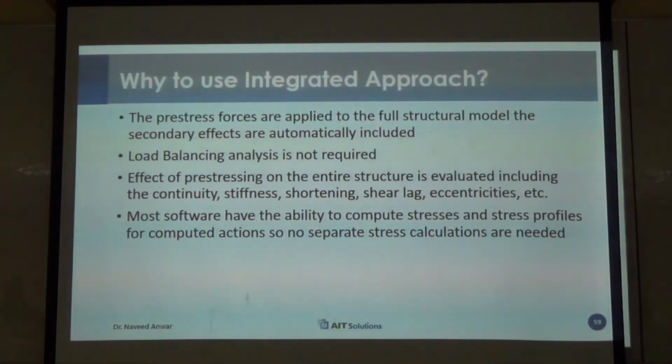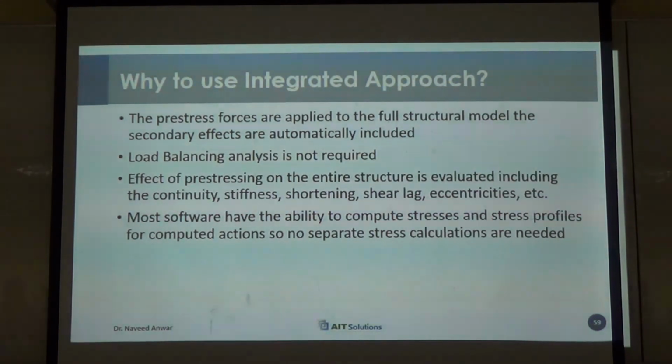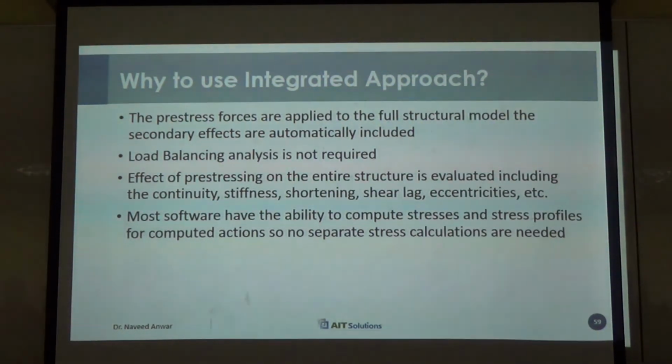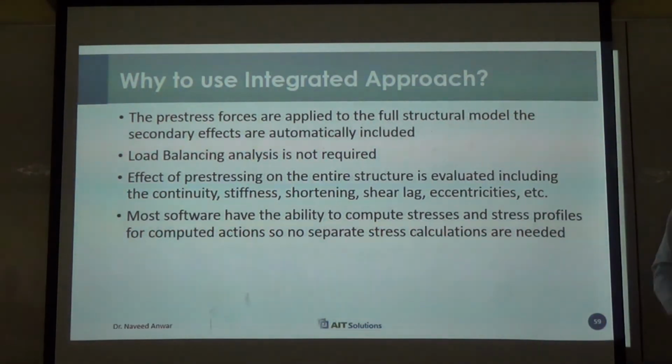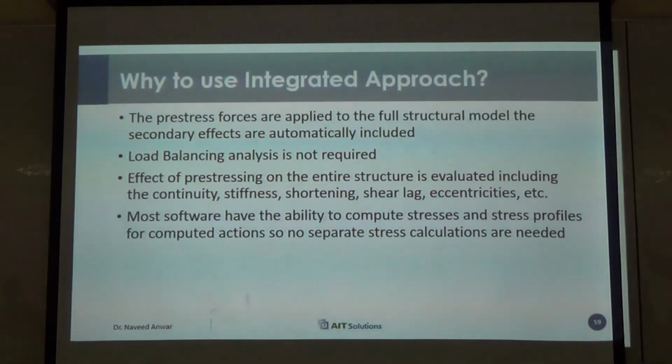It's really the most complicated part of the concrete bridge, to handle pre-stressing properly, because it has long-term effects. It can change the reactions on the bearings. It can change the deflections. If the segments have been put together and the pre-stressing is lost, the bridge can fall down. So there are many consequences of not handling the pre-stressing properly in a bridge. It's way too advanced to be covered in this course.